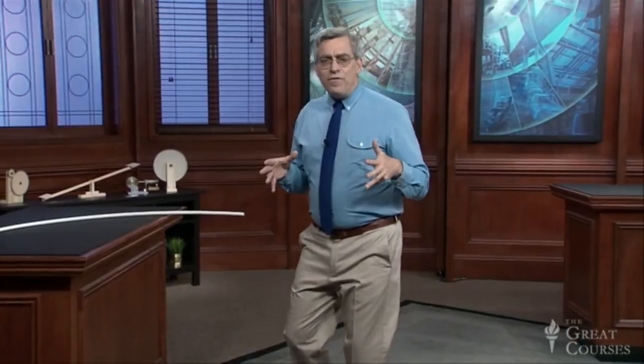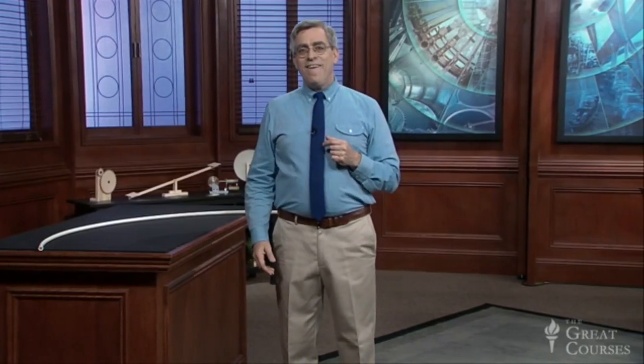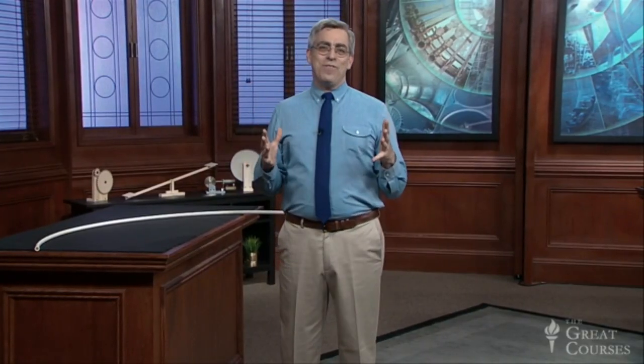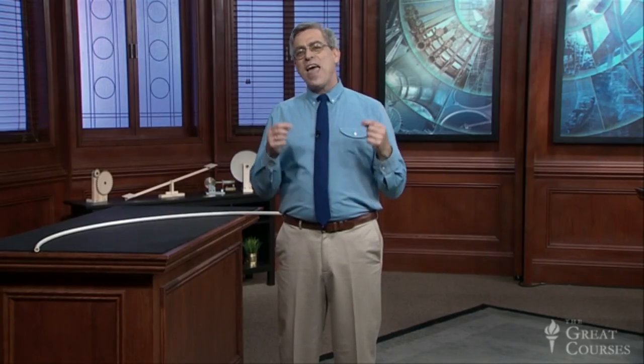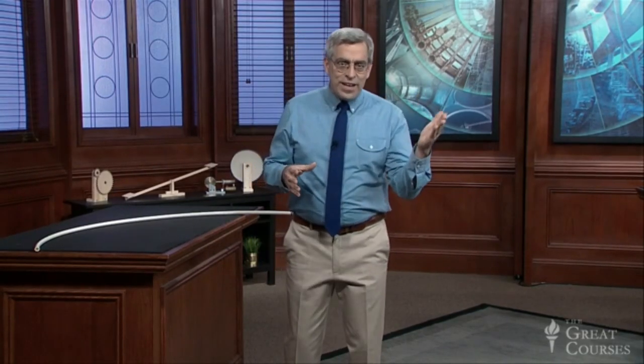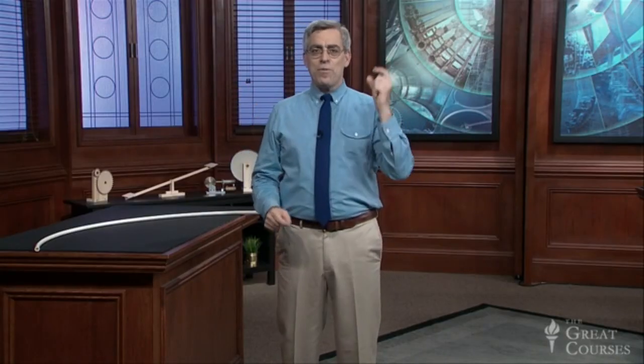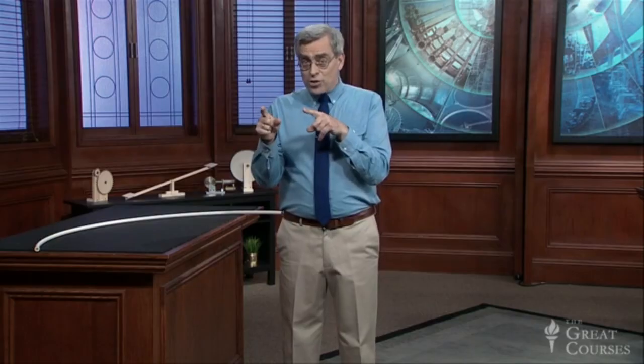Heat pump systems have the added advantage of using one set of ducts for heating, cooling, humidification, and air filtering, just like forced air systems. Now, as an engineer, I can't help but feel a certain affinity for this sort of elegance in engineering design, for this system's ability to deliver either heating or cooling using essentially the same mechanical apparatus with the flip of a switch. Modern heat pumps also have very high thermodynamic efficiency. For these reasons, in moderate climates requiring both heating and air conditioning, a heat pump can be quite cost effective.